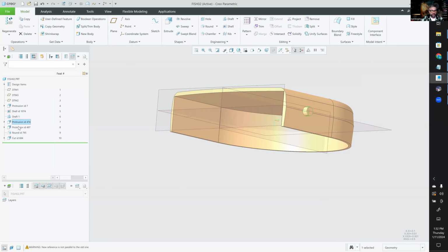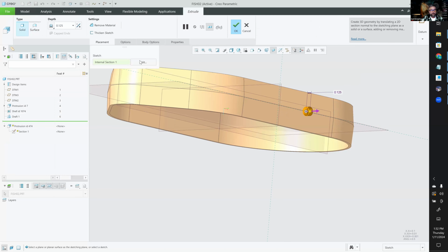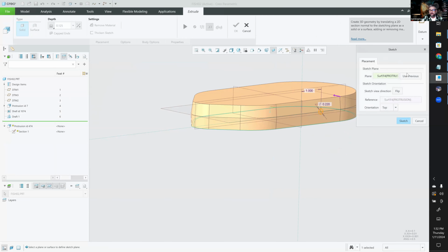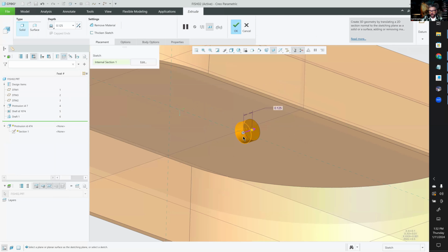Here, I'll just use edit definition to get the sketch to occur. Let's see. I'll put it on the center datum plane. This will look a little awkward. So instead of on the side of the part that's got draft on it, I'll make it go to the center datum plane. That's awkward because my extrude isn't going to be long enough.